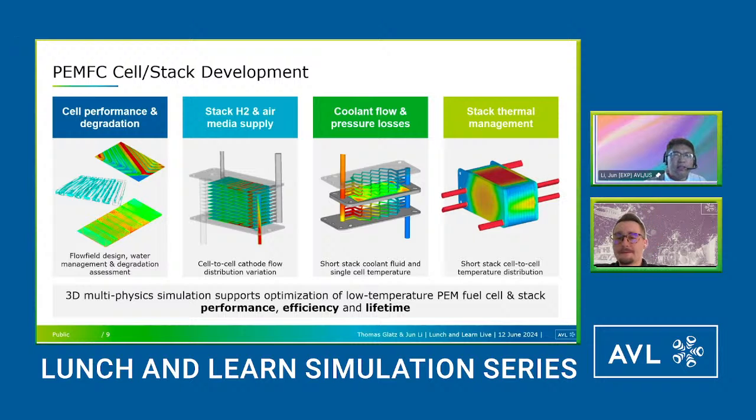Yeah. So I think basically with 3D, we are trying to solve the flow and media supply problems, and also try to solve, for example, the water management issues and the local degradation possibilities. With that goal in mind, our tool can be applied, for example, in these slides, to the cell performance and degradation for the cell. Then for the stack, here we can solve the hydrogen and air supply, and then for the thermal management system, we solve the coolant flow and pressure loss, and then for the stack thermal management applications. Yeah.